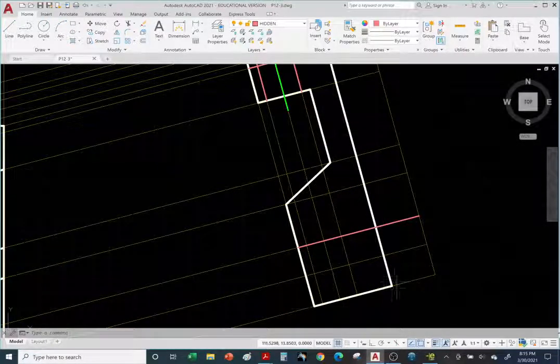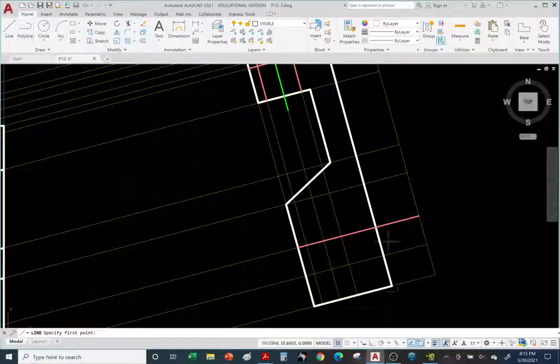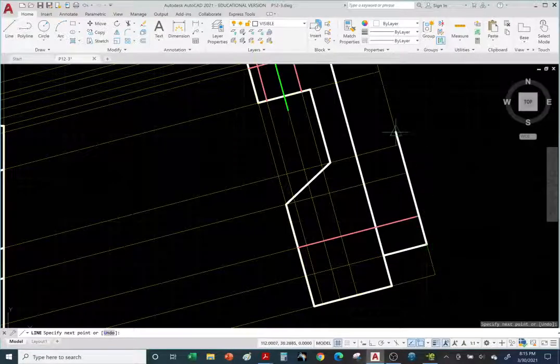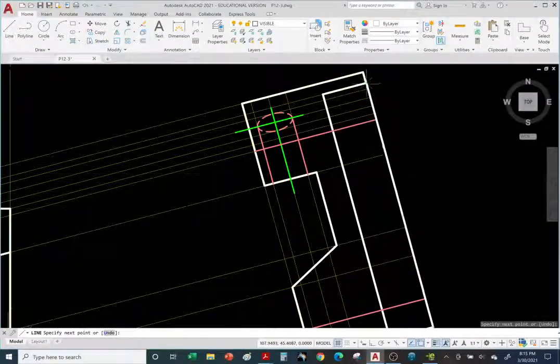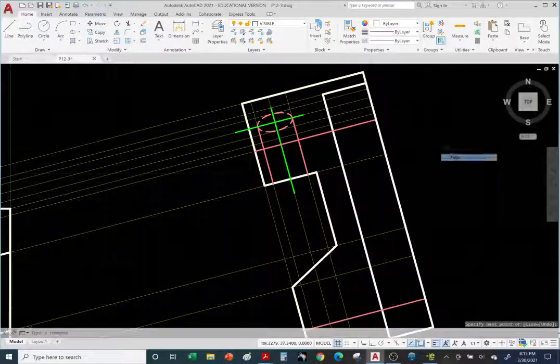Okay, there it is. So now from down here, we're going to draw an object line from here, and then we'll go up. Okay, so let's go to the visible object layer and line command. And notice I have ortho off. Okay, so I'm going to go from this corner to this intersection point and work my way up. And there it is, right click enter.